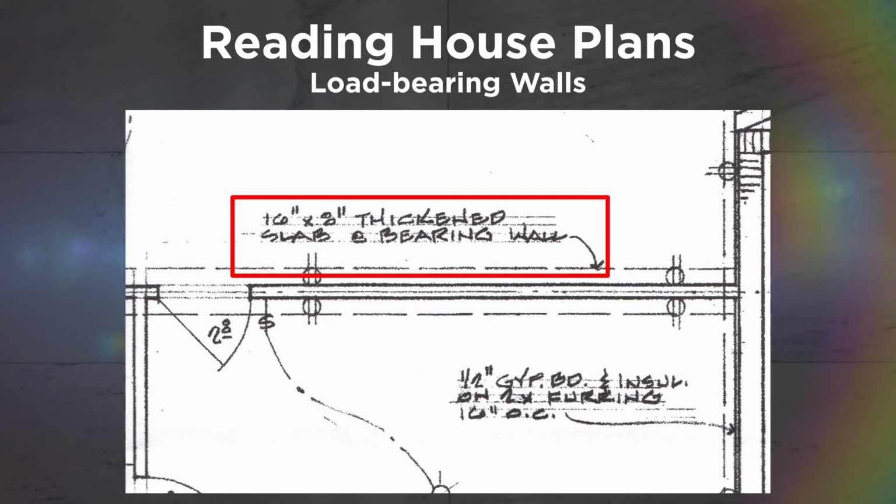Well, these areas would indicate where load-bearing walls will be placed once framed walls are added for the first level. In our plan, we see that notation in the wall separating the back of the house from the front of the house. The slab is to be thicker in an area 16 inches wide and 8 inches deep. This thicker portion of the concrete slab will act as a footing for interior load-bearing walls.